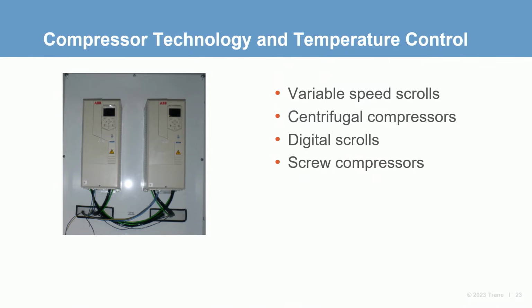Modular designs often have flexibility in how many variable speed compressors to utilize in your design. 1 or 2 variable speed compressors make a large impact on a single module, but adding more variable speed compressors has diminishing returns in a large chiller bank.